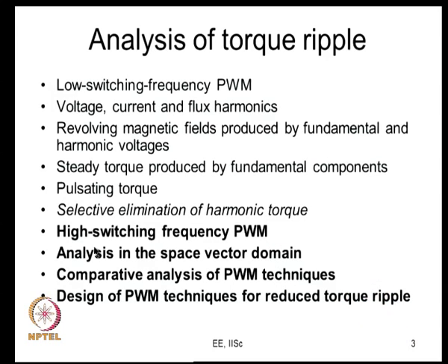We will look at it from the space vector point of view, because that is more general than the triangle comparison, and we will be dealing with certain space vector based PWM methods which really cannot be implemented from the triangle comparison mode, which are different from that. So, we would look at a few advanced bus clamping PWM schemes too here.